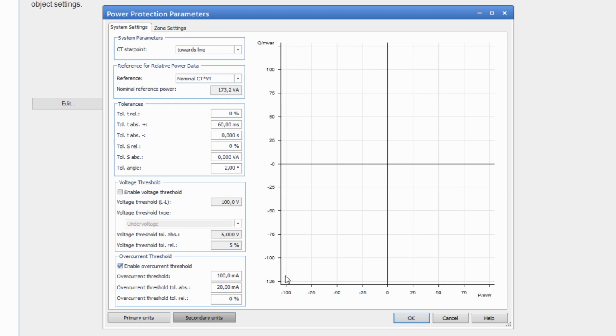The undervoltage criterion will be considered later in our test by defining a constant test voltage of 85% of the nominal voltage. However, we enter a value here to allow for an automated assessment of the test module. If we do a cross-check with a higher voltage value, then the relay should not trip. In the next step, we will enter the power characteristic.